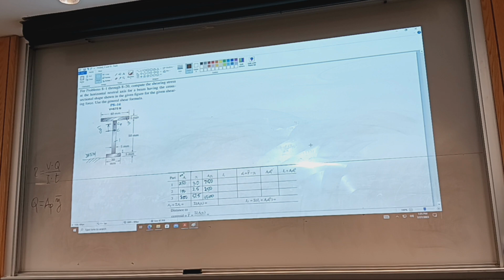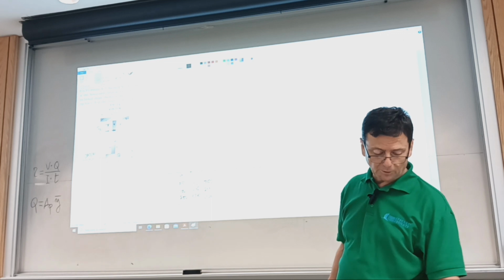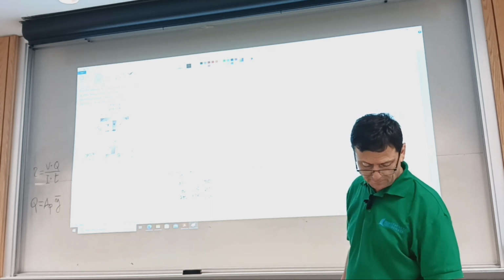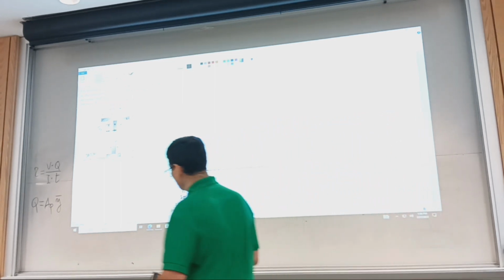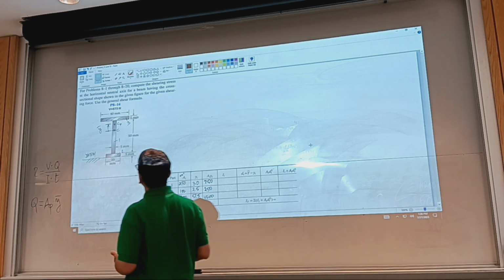All right. So we saw this before. It's b h to the power 3 over 12. This is Appendix 1, page 783, or rather 53. So for the vertical web, we have 5 times 50 to the power 3, over 12.